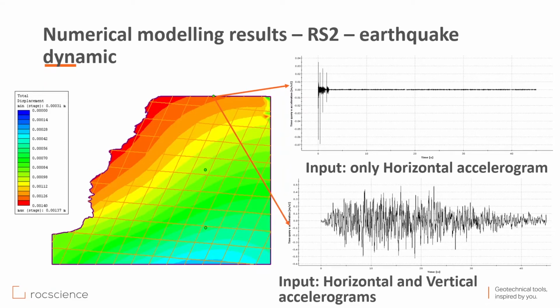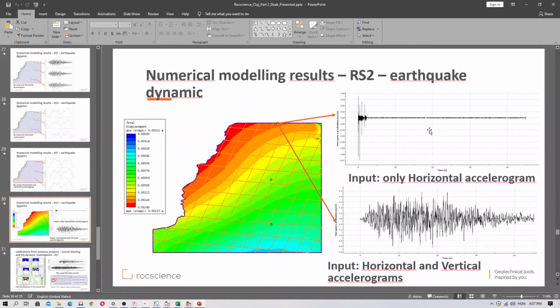The stress redistribution on the discontinuity boundaries is solved, and the physical conditions of the discontinuities are defined in a different solver than the continuous material. This behavior is also observable when dynamic examination is used. So the attenuation and amplification of the waves is blocked or staggered abruptly as they pass through the discontinuities, and this result is visible here exactly.